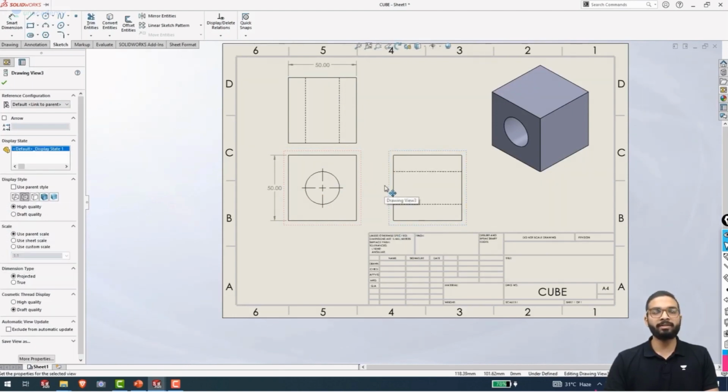Now it is very clear that this cube has a circular hole in between. Or rather, you can read it from here that there is a feature which is not on the surface, but there is something on the inside. You can read all of these together, and then you figure out that there is a through hole in this cube. This is also very clear from over here, but it was not clear that this is a through hole. This view and this view over here show you that the hole is completely through the surface or completely through the body.